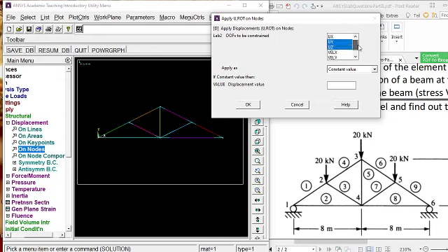So I am just saying that UY, UZ, and the velocity x, y, z all being arrested means that the UX direction is allowed to go for expansion or something like that. For these two nodes we are talking about. We are not talking about any other nodes. Only the first and last we are talking about. We are not talking about other node points or other key points.